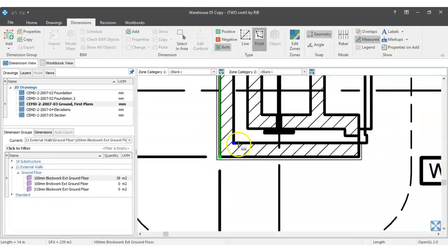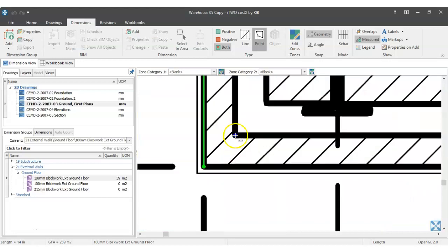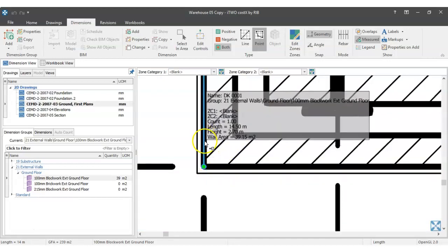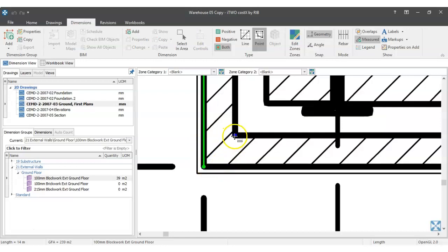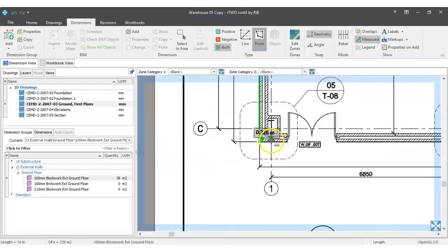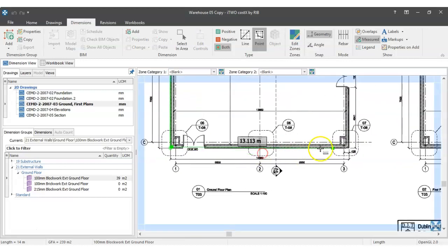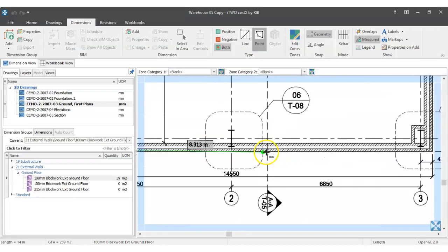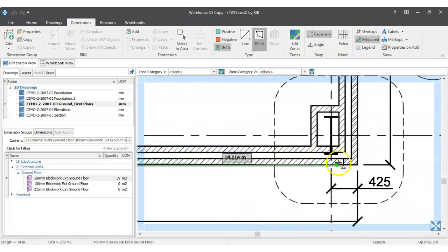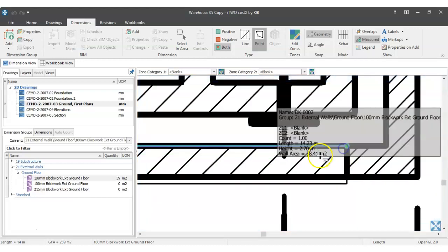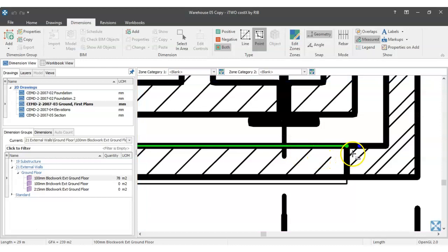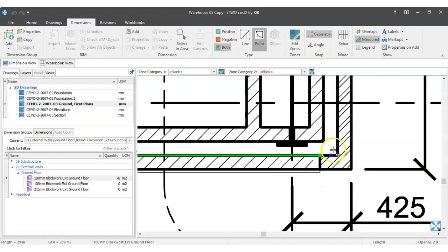Okay. Now what I'm going to do is measure from this side. I'm not going to start here or here, because then I'm double measuring that corner. So I'll go from outside to inside, and that's good practice. The more you get used to this from a quantity surveying point of view, the better. So I'm still on my outside, and see there, that's where my block wall stops on my outer leaf and my brickwork begins. How do I know that? Well, this is a double hatch line, and this is a single hatch line.